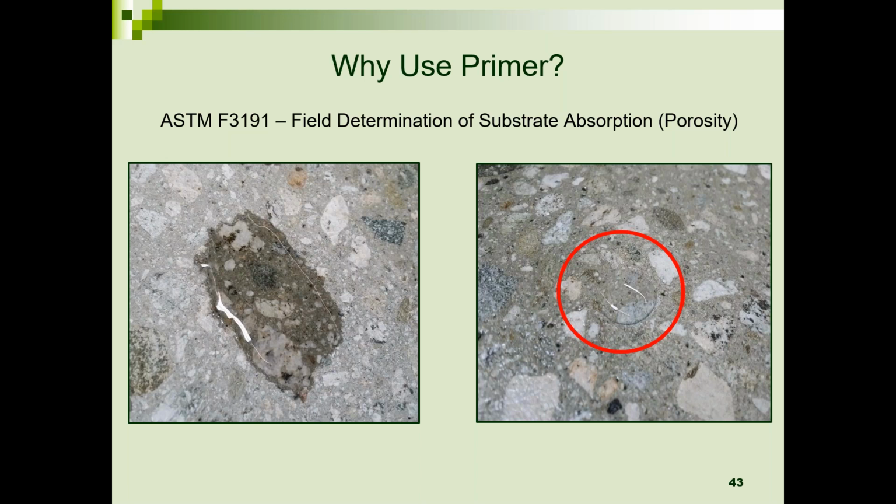There is some visual indicator on how porous or how dense a concrete surface is and how much surface prep you need to do. So if it's a repelling substrate, as we see on the right, depending on the manufacturer, you may have to do some mechanical prep on that surface. On the left, if you find that it readily absorbs in, you may get away with minimal prep, depending on what the manufacturer represents. But a drop of water on a concrete substrate answers a lot of questions, some questions they may not be thinking about. Again, the simple test to evaluate porosity absorption of a concrete substrate.